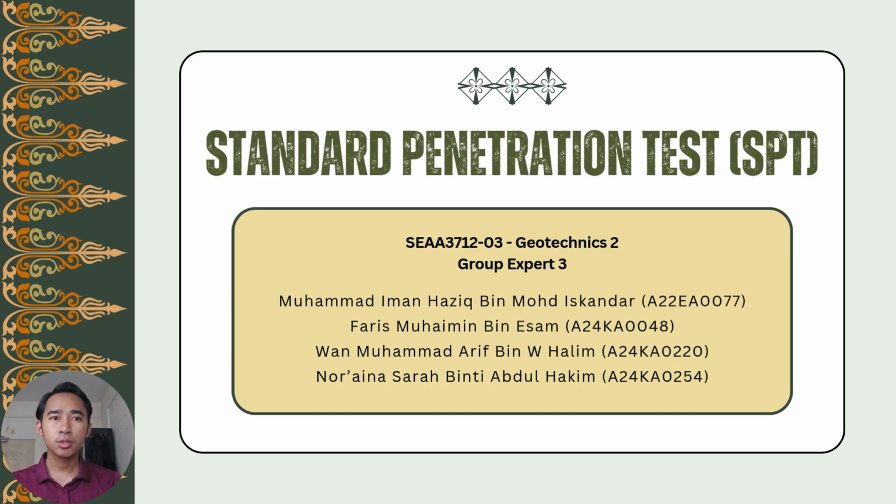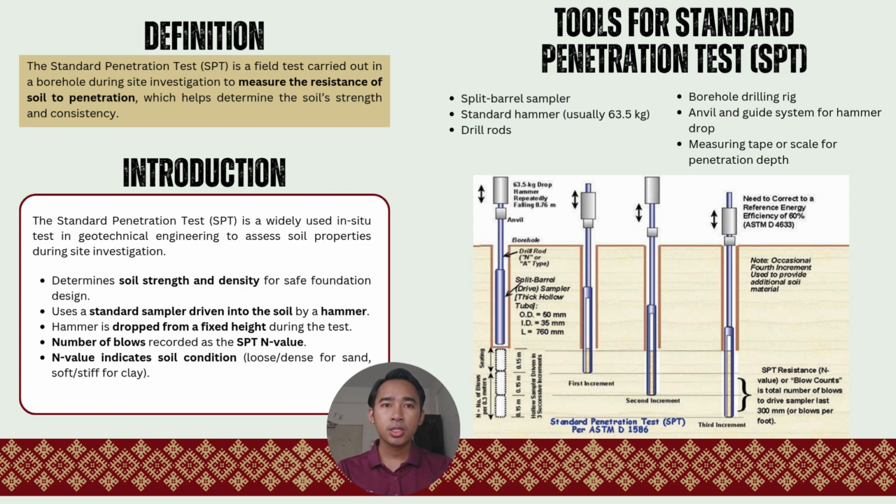As a representative of Group Expert 3, today I would like to explain about the Standard Penetration Test, commonly known as SPT. So, what is an SPT? It is an in-situ field test conducted within a borehole during site investigation. Its primary purpose is to measure soil resistance, which allows us to determine the strength and consistency of the subsurface.